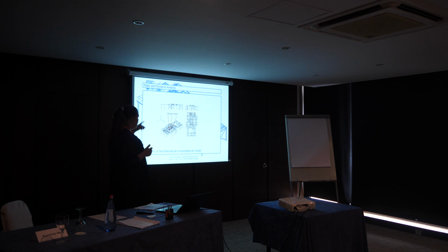We applied forces in the spots of the robots, and we computed displacements. After that, we computed rigidity in all directions. The rigidity was satisfactory only in the Z direction, so rigidity and stiffness in directions X and Y were not satisfactory.